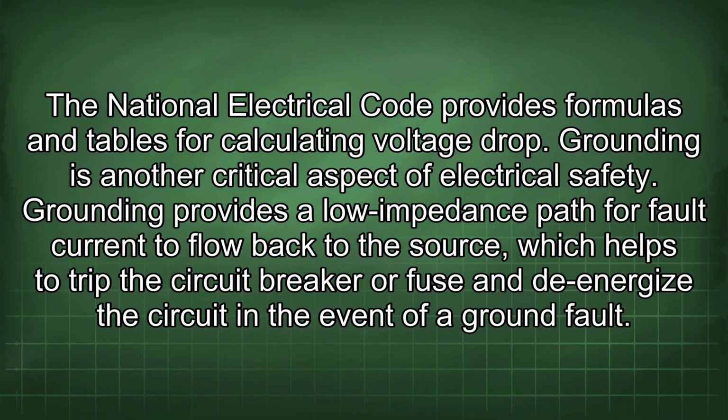Grounding is another critical aspect of electrical safety. Grounding provides a low impedance path for fault current to flow back to the source, which helps to trip the circuit breaker or fuse and de-energize the circuit in the event of a ground fault.